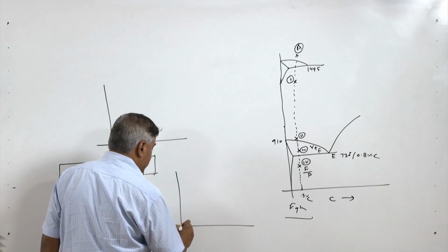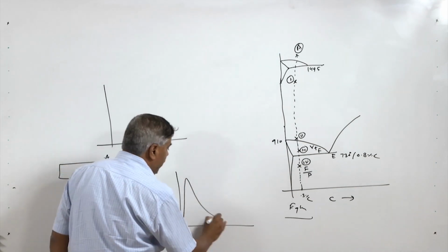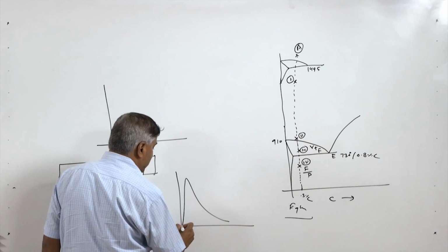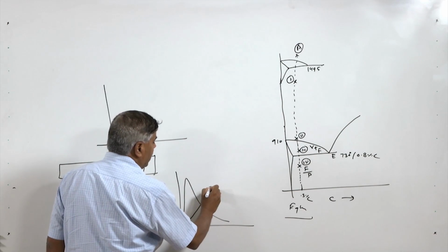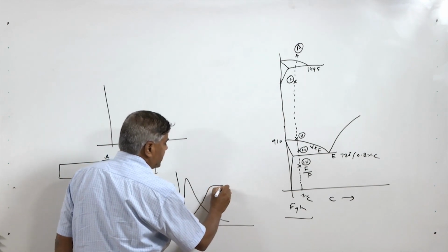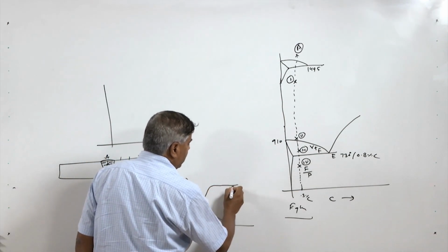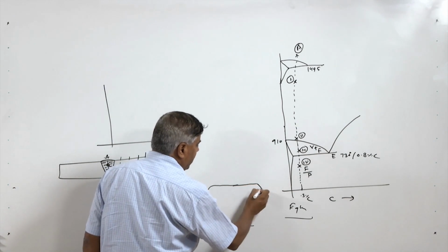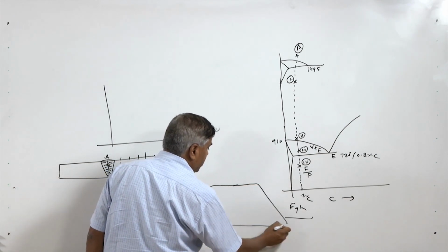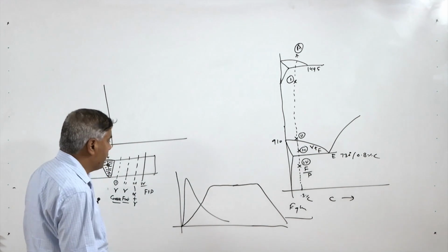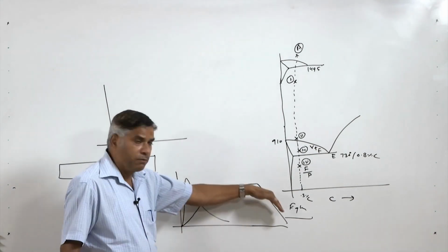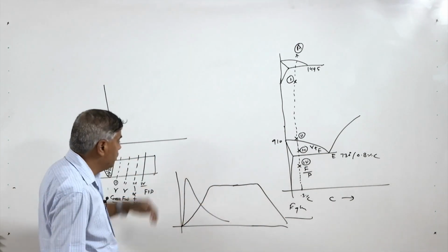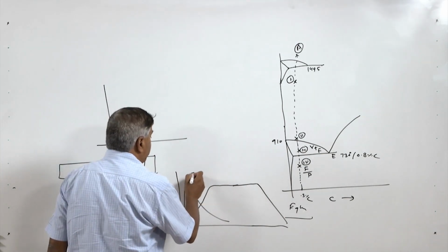The weld thermal cycle experiences a much higher heating rate followed by rapid cooling, while in the case of heat treatment it experiences a lower heating rate, then a steady state, followed by controlled cooling as per the kind of heat treatment performed. So exposure at high temperature is for a much longer period, and the rates of heating and cooling are slower as compared to those experienced under welding conditions.